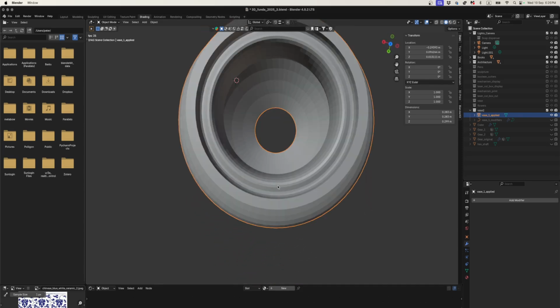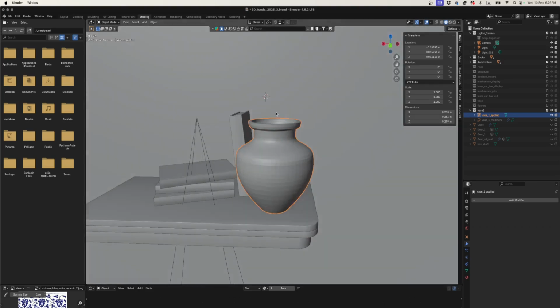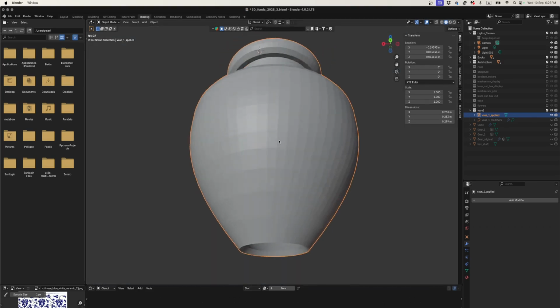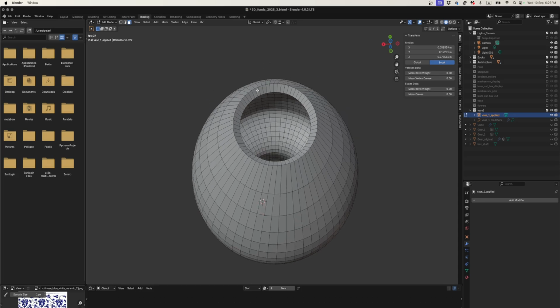The reason there's a hole is just the way that our screw modifier worked. So I've just pressed the question mark button here to isolate select, and I'm going to go into edit mode, and I'm going to press 3 to make sure I'm in face select, and I'm going to select all of these faces, and I think it's shift command left click. Okay, it selects the distance between the last 2 clicked, and then I'm just going to press X and delete the faces, and now I'll go into edge select by pressing 2, and I think maybe shift option click.